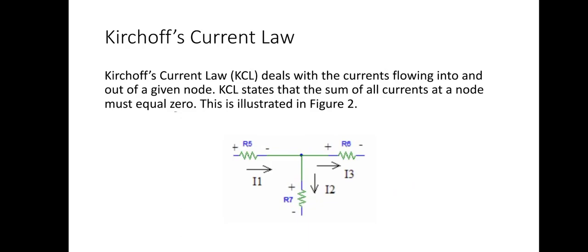Like for batteries, the voltage change is positive when summing from negative to positive, and for resistors the voltage change is negative when summing in the direction of the current, also known as sign conventions, which are used to solve problems. Kirchhoff's junction law: the first two can be calculated using V equals IR. Like V equals IR is a basic formula which we need to be reminded of every time we use Kirchhoff's law.